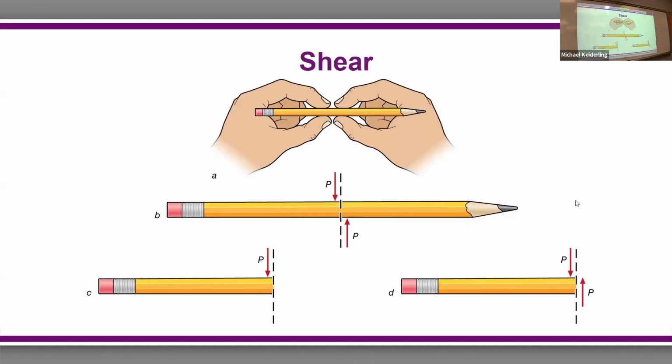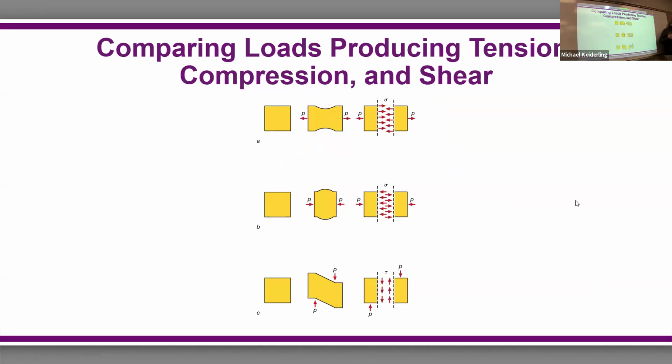And here, this is like a piece of paper. A piece of paper is strong in tension, weak in compression, and relatively weak in shear. That's what you do to tear things, is you shear them. Yes, they're called shears. The force that shears apply is shear. So one side goes down, the other side goes up, you have a shear force.